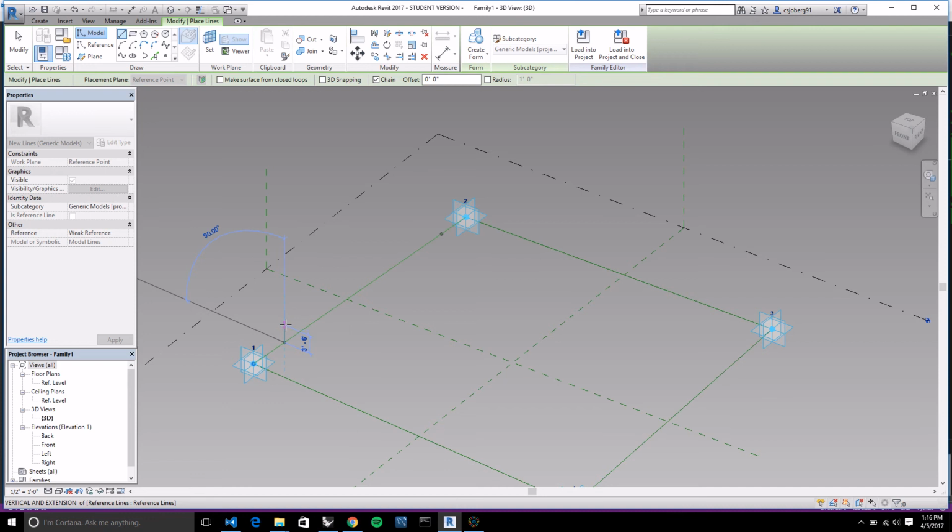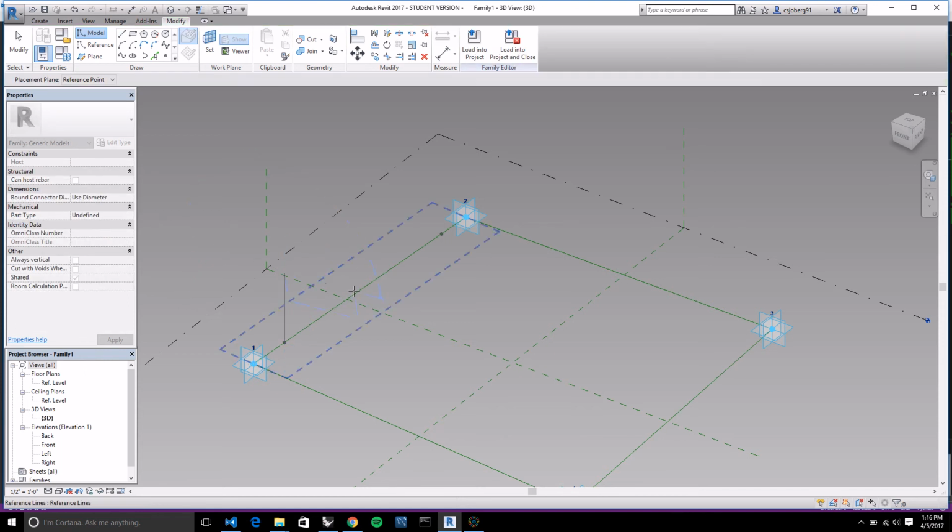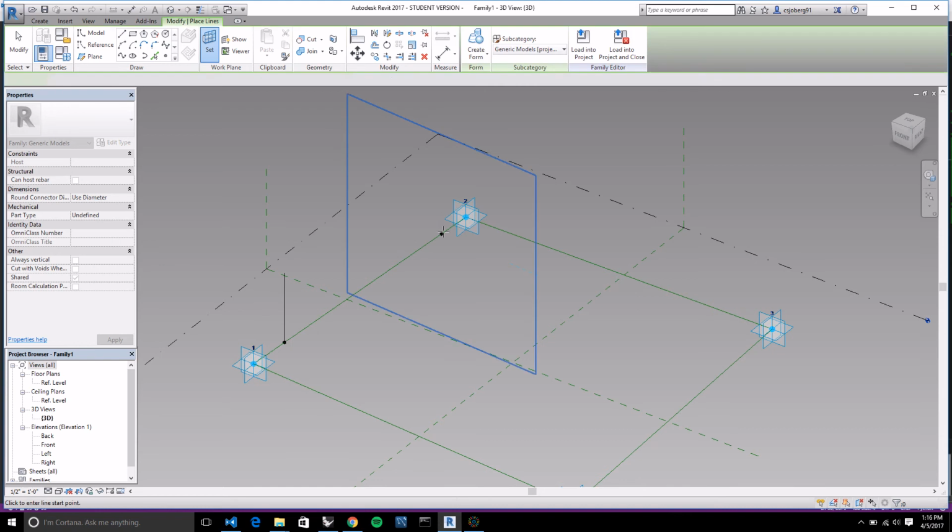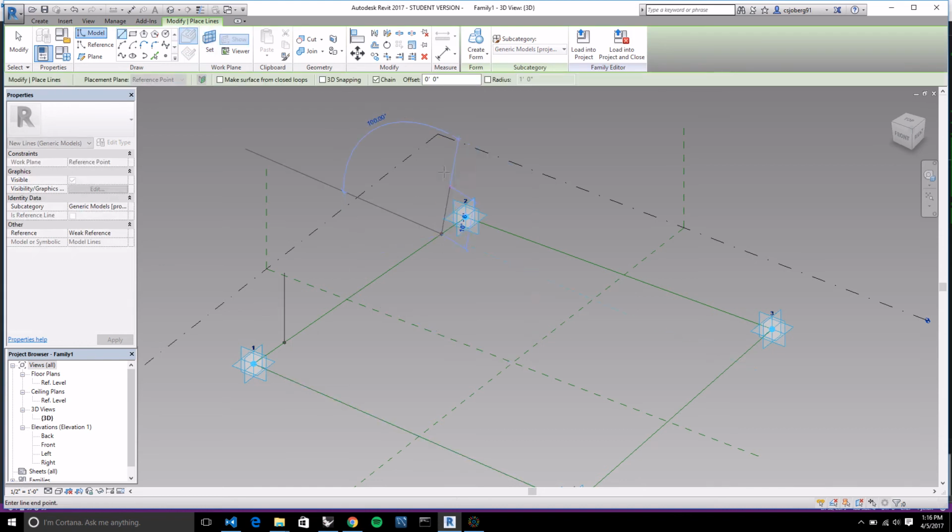and really this is a much larger panel than I need it to be, but for the sake of being able to see it, I'll keep the panel around, we'll say 14 feet. You can really enter anything you want. We'll modify this later. And then what I'll do is I'll come over here and say set reference plane again, and I'll click on the other point. You can select draw a line and do exactly the same thing we've done in the previous one.